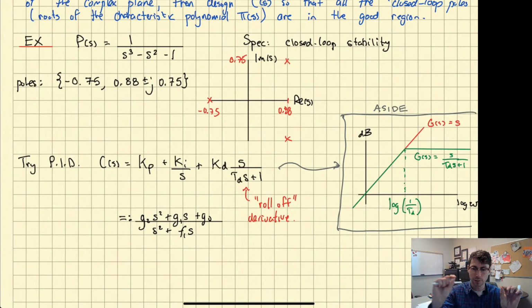If I give you a function of time and I want to take its exact derivative, I need to know what it will do in the future, because remember, the derivative is a limit from two directions. So ideal differentiation requires future information. You can't implement that in real time, because right now, whatever information I've acquired, I don't know what will happen in the future. So I can't implement an ideal differentiator. It's unimplementable, non-causal, and needs future information.